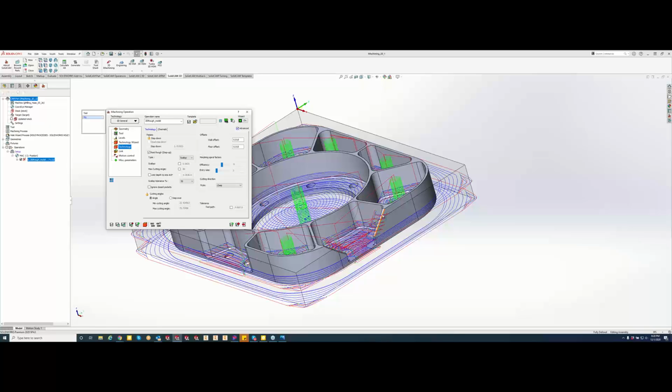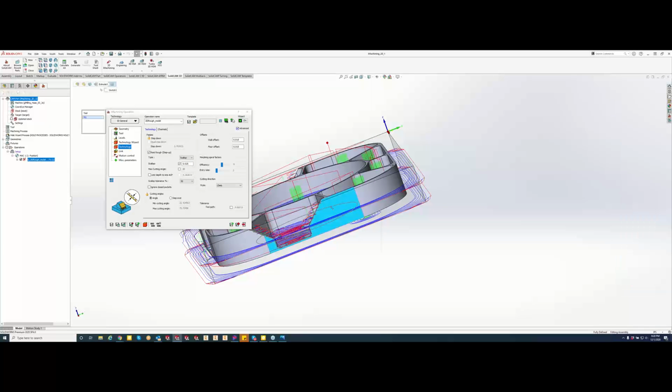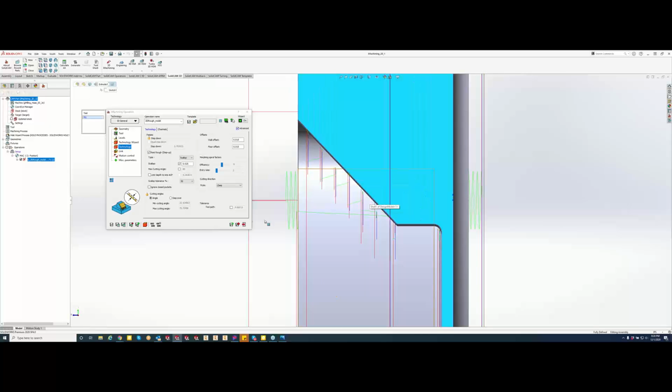You'll have less of a scallop there, which is going to lead to uneven load on a finishing end mill when it's coming in there and going back and forth. Now, you can change the scallop in here. If we're looking for something really small, we can come in here and do a 25 thou scallop. Now take a peek. Let me get a side view here. When we go to save and calculate this, it's going to add quite a bit more tool path just on this 3D pass right here, because we're basing it off of the scallop height, 82 thou versus 20 thou. So we should see a lot more passes going on right here.